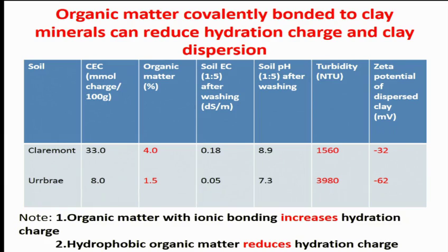Whereas if the organic matter in the soil is ionically bonded, free molecules with a negative charge will increase the dispersion. At the same time, some organic matter can be hydrophobic. If the hydrophobic organic matter covers the soil charges, then the water molecules don't react, therefore there is no increased dispersion. The dispersion is reduced.